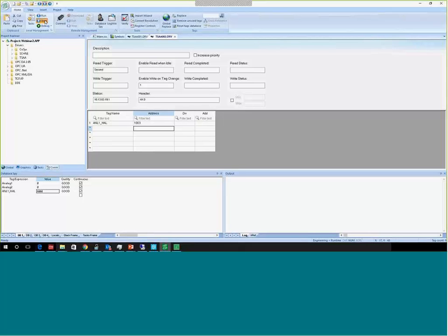There are OPC servers available for Triconex PLCs. There are DDE servers, even OPC UA. Just keep in mind, depending on the project, mainly if you're going to go on an embedded system, it would be hard to install some of these features. So you can use InduSoft Web Studio with our TSAA driver on those systems as well.